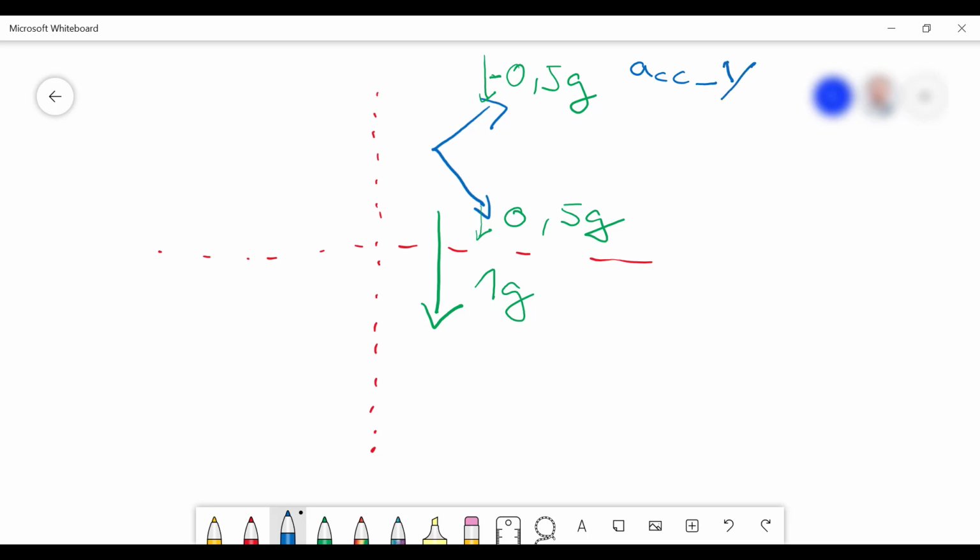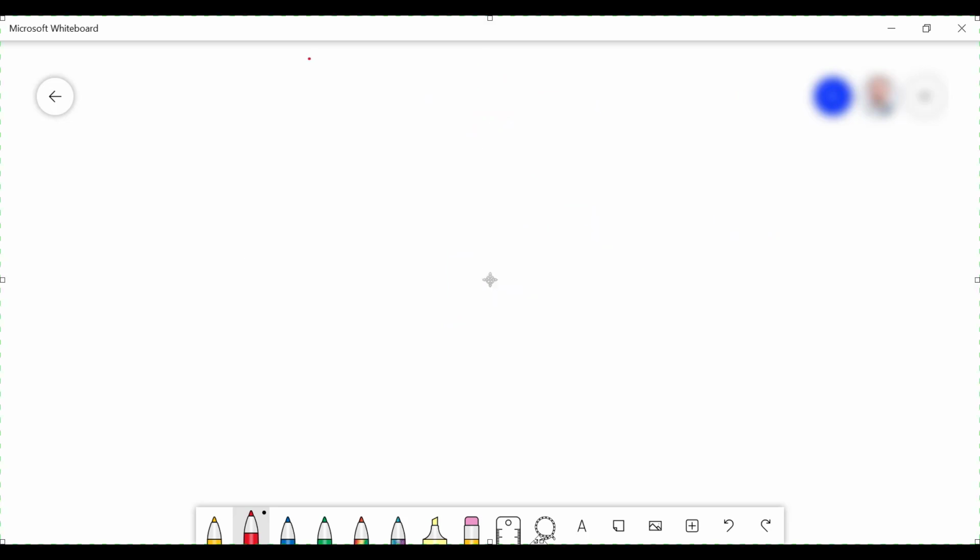And that's what is provided by our sensor. Our sensor provides the y vector information in g, the x vector information in g, and the z vector information in g. So for this simple example, y and x would be enough for us to calculate this angle here. This is the rotation angle, let's call it theta, about which the system has tilted. We get it in g, but we need to calculate the angle. For that we need some trigonometry.